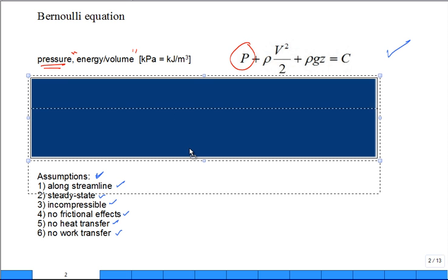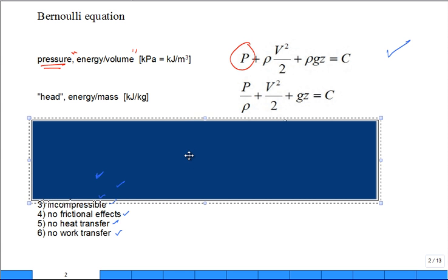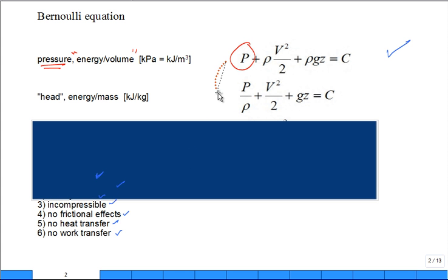If I take that equation and I divide everything by rho, I get a second equation. The second equation looks like this. You say, all I did was divide by rho. You're absolutely right. That's all you did, but did you get any insight in there? Sure, because we look at each of those terms, and we look especially at this term, and we're reminded, maybe not as clear as P was pressure, but this term is V squared over 2. It's specific kinetic energy. Coming out of thermo, specific kinetic energy, meaning kinetic energy per unit mass, or a form of energy per unit mass.